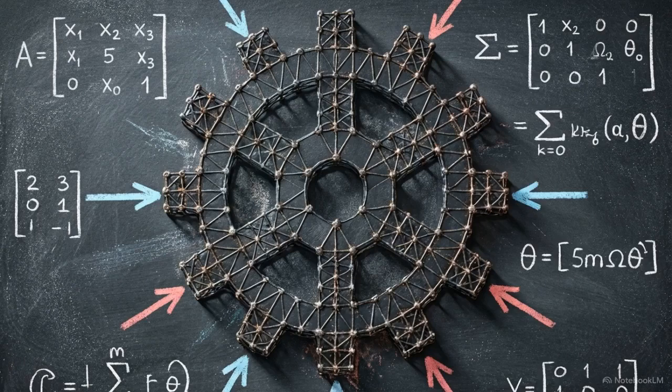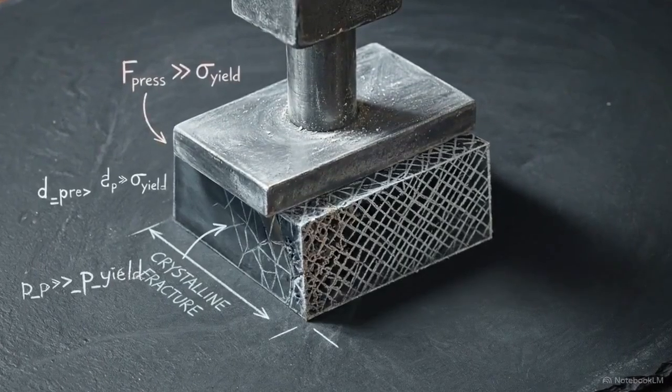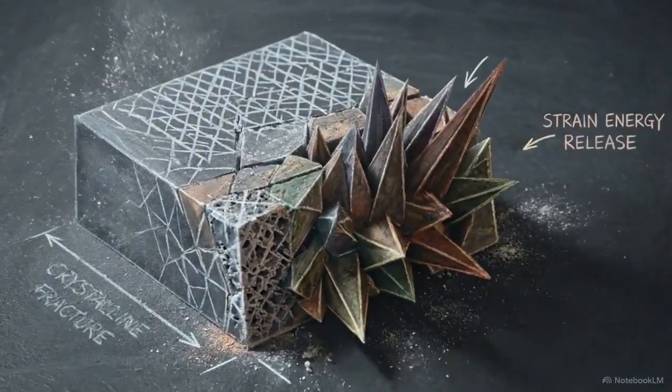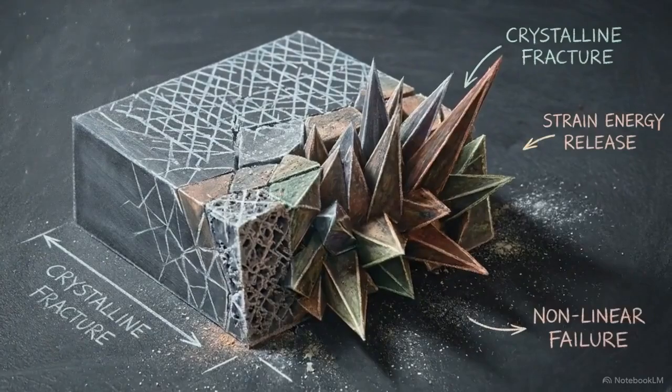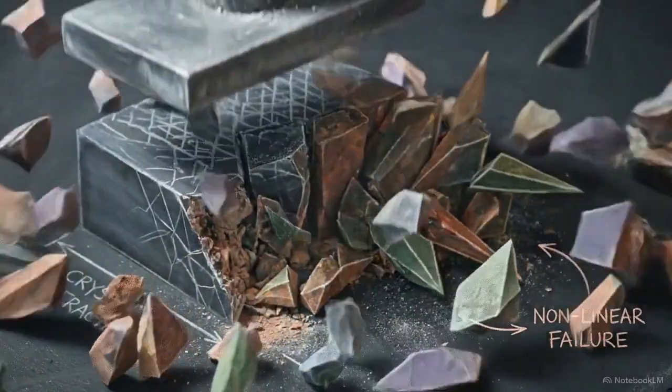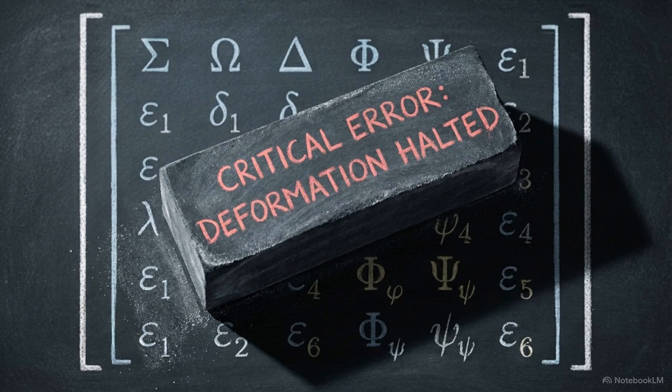Finite element analysis, or FEA, is a computational method used to predict how structures react to physical forces. It usually relies on standard Lagrange elements, but when we push these classical displacement-based models toward nearly incompressible limits, like simulating hyperelastic rubber, the math breaks. This failure is called volumetric locking.